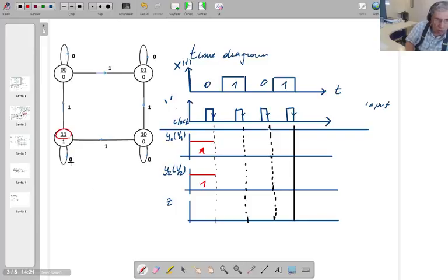I'm going to observe that 0 here, in a different color. So I can draw the other z values, because z is equal to y1 and y2 multiplied. So the next state, 1, 1: if you apply 0, my next state is the same, isn't it? When the present state is 1, 1 and you apply 0, you come back to that. So my next state is 1, 1 again.